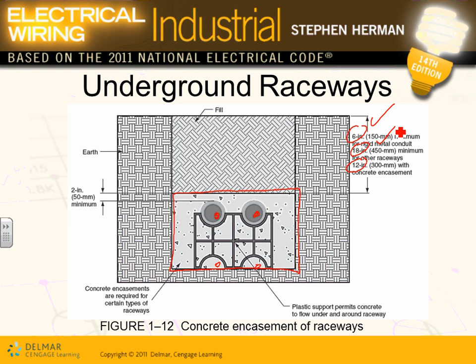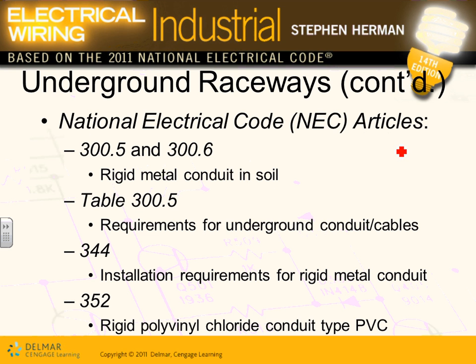So here's the different elevation: if you have rigid metal conduit, 6 inches; 18 for conduit by themselves; if you encase them in concrete, all you need is 12 inches. And typically in a 4,000 amp switchgear, guys, that's what they do. In a 4,000 amp switchgear, they encase them in concrete. So all this information, guys, is coming from 300.5, especially Table 300.5, the requirements for the elevation underground. So please refer to this one.